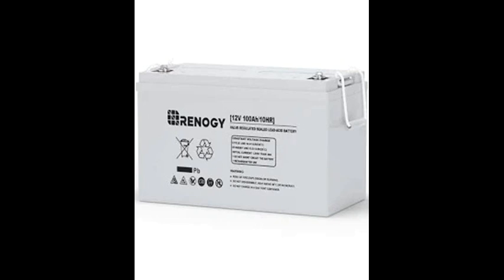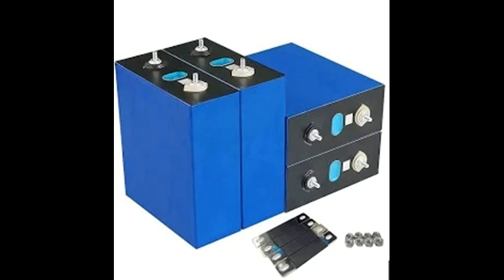For instance, lead acid batteries only have 50% of their rated capacity that's usable. That means that a lead acid battery that is rated at 100 amp hours only has 50 amp hours that is usable. On the other hand, if you're using lithium iron phosphate cells, not a battery, but just the individual cells, and you make your own battery, lithium iron phosphate chemistry has 80% usable capacity. So a 100 amp hour lithium iron phosphate cell would have 80 amp hours of usable capacity.